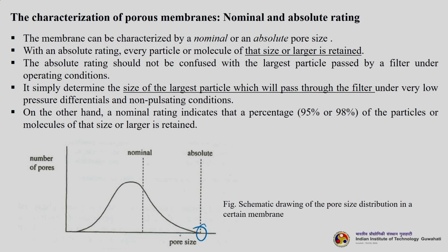every particle larger than that size is retained on the surface of the membrane, compared to what? Compared to the pore size. The absolute rating should not be confused with the largest particle passed by a filter under operating conditions. It simply determines the size of the largest particle which will pass through the filter under very low pressure differentials and non-pulsating conditions.